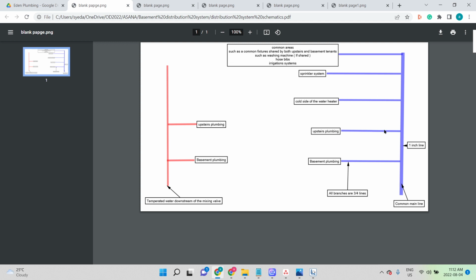the water. And if they shut off the water, let's say you have a leak upstairs and you have a fire down, now the sprinkler system is not going to get activated because there is no water. You have a big problem, right? If I do connect it to the basement plumbing, again, same thing. If I shut off the water, I cannot connect the sprinkler. There will be no pressure in the sprinkler system.